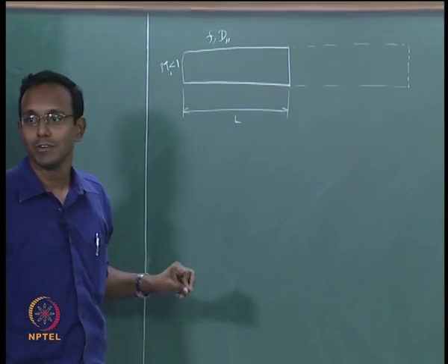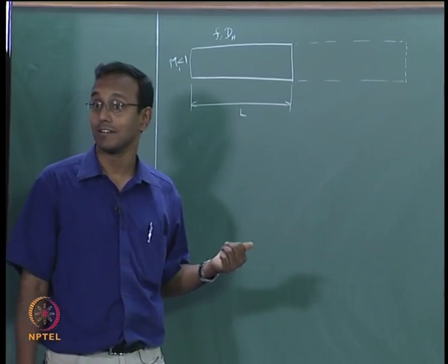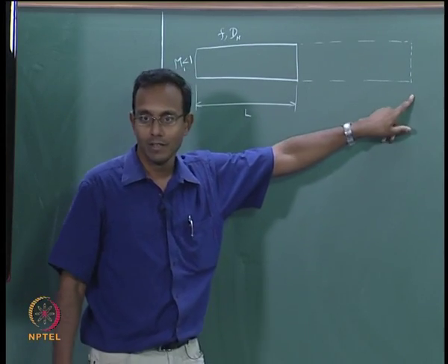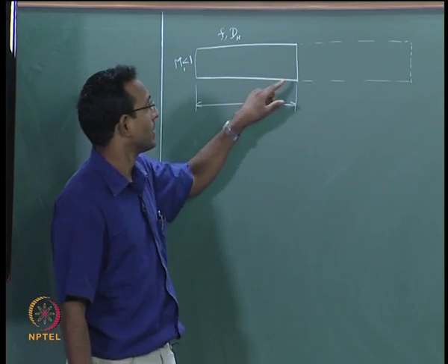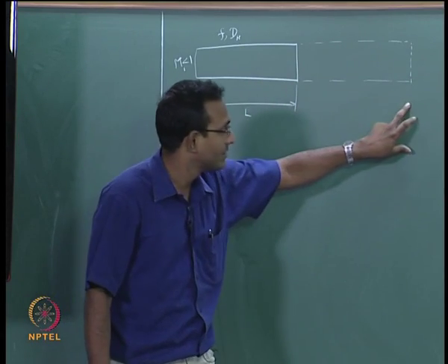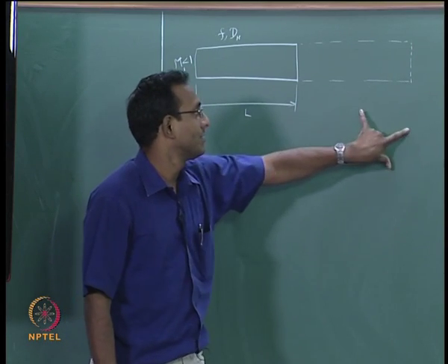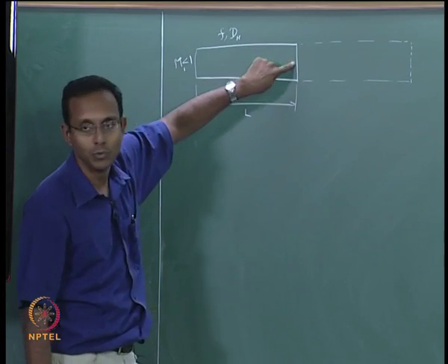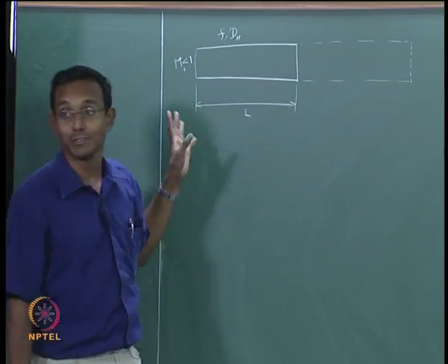Now we will look at it similar to the way we did the expansion fans, Prandtl-Meyer curves. I am going to say from M1 it is going to reach Mach number 1, and somewhere along the way it reaches M2. Now if I think about M2 as my starting point, then it will take exactly this length to reach this L star. So this length will be that particular L star for this exit Mach number M2 for this particular problem. That is the way I want to think about this. This is the way to solve the problem.